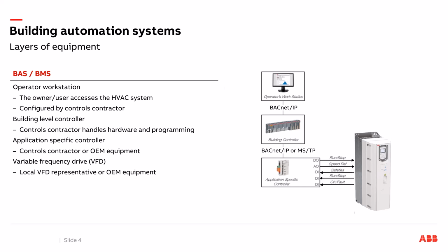Application specific controllers are typically provided either by the controls contractor, or sometimes the OEM equipment. The VFD is typically provided by the local VFD representative, or sometimes as part of the OEM equipment. But you'll notice as we start at the top of that image and work our way down, there's BACnet allowing all these devices to talk to each other. And we'll get into that. When you get down to the application specific controller and you look at that drive in the bottom right, there's a lot of different ways you can control drives and devices like drives. The old way of doing it, and we'll get into it in a little bit, is using analog signals and start-stop, just on-off type signals. You can also do that all over BACnet, or you can have some mix of that control over BACnet.